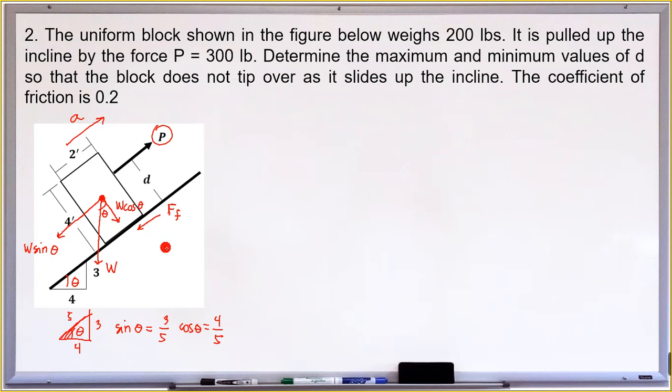Again, if the object rests on the surface, then by Newton's third law, the surface exerts a reaction force. So there is a normal force acting, and this normal force should coincide at the center of gravity of our body. So normal force, and again this is our CG, center of gravity. So by having this, we have obtained all the external forces.